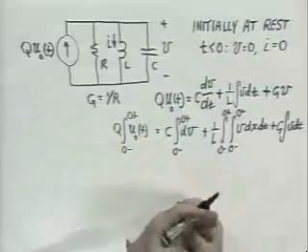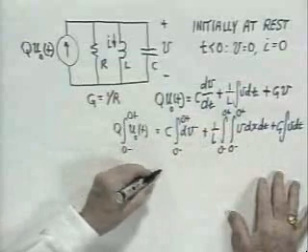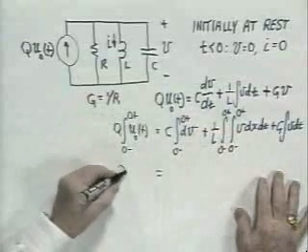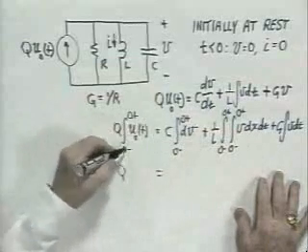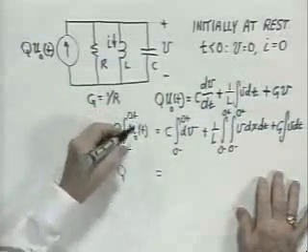Well, with that equation, we can now interpret what's happening to the three terms on the right. The term on the left is just Q, because the integral of an impulse through the origin is the area under the impulse. That's just 1 by definition for the unit impulse.